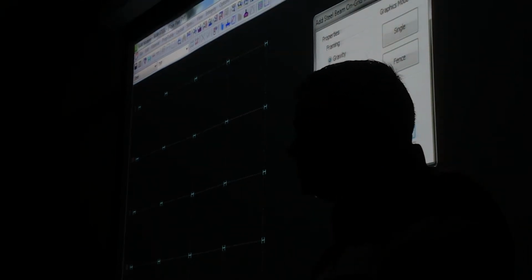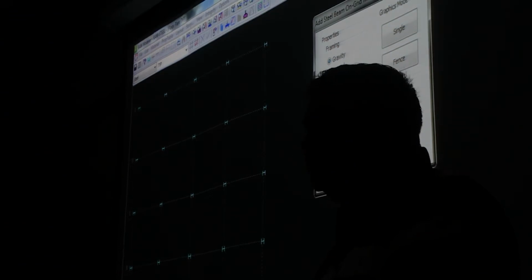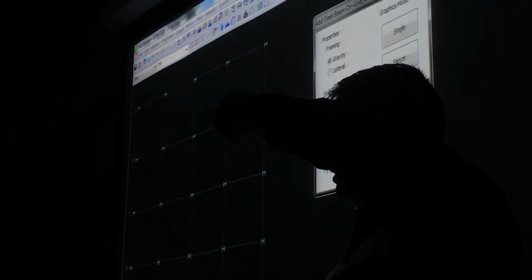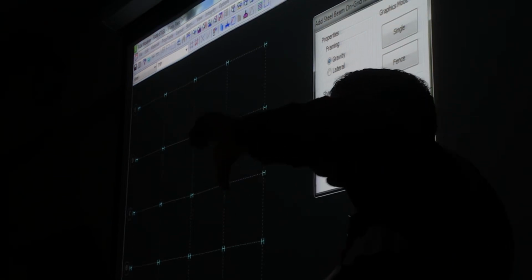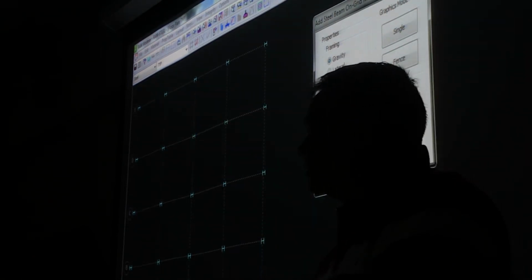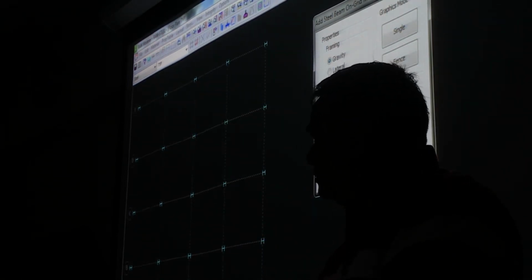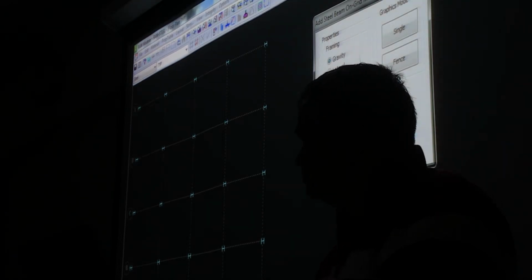If you have a negative bending, say for example moment frame or brace frame, you'll have a negative bending because it goes laterally. So your bending moment diagram, half is in positive, half is in negative. That's not going to work. Unless you're putting concrete, right? What do you mean by that? So let's say you pour the concrete and then you separate at the point where the moment changes, then you have two positive moments for the concrete.